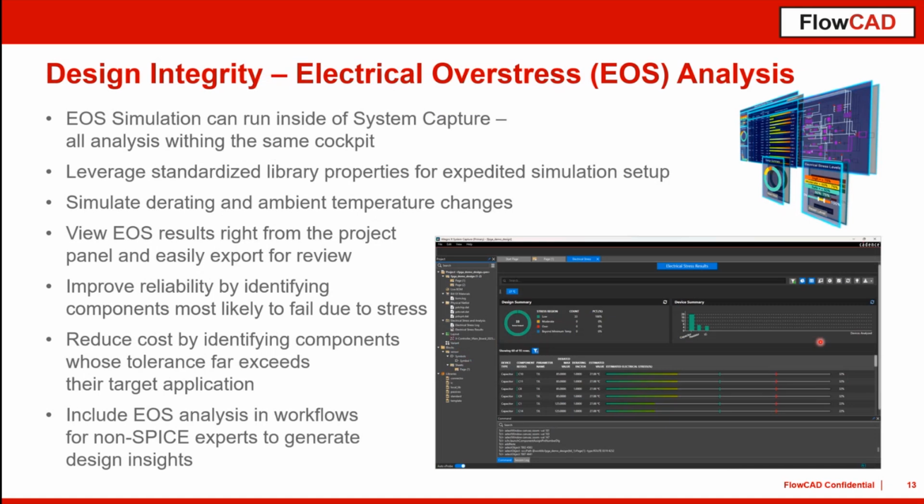Design integrity overstress analysis. This is directly built into System Capture, and the good thing here is that non-SPICE experts can also use it. So you don't have to take care of too many things. For sure, the tooling is using properties from the library for the simulation. Then you can have a look at your components and see whether some of the parts inside of your design might get too stressed and therefore fail earlier. So this is a nice analysis which is directly built into System Capture.